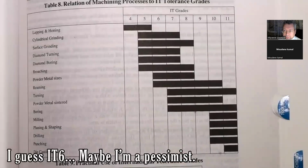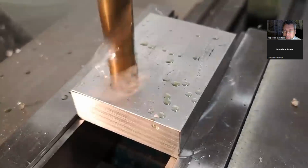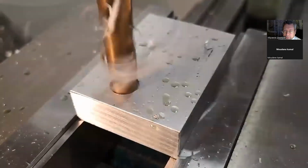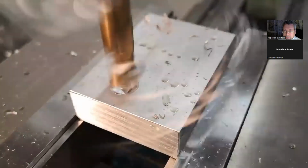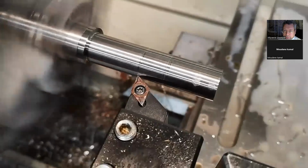Likewise, if you have to design something to fit inside a drilled hole, even if you don't have the tolerance for the hole in front of you, you can look up drilling and see that it has at best about IT10. So the whole basis for the fit is going to be around H10. So why would you use this system? Personally, I like how much information is available through just 2 digits.